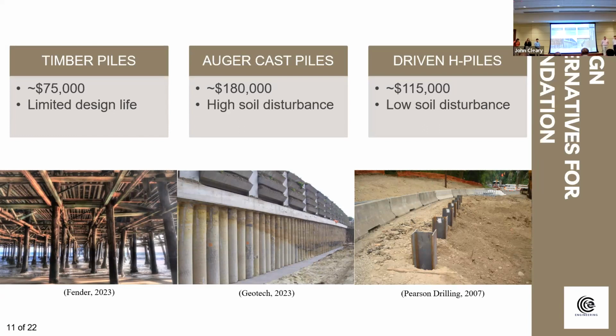So is that what you're referencing here? Yeah. Okay, because with driven piles, the vibrations from the hammer are going to disturb the surrounding soils. So I was kind of confused how you had that as low soil disturbance. You're talking about actually removing soil versus not. Yes, right, not moving soil. Okay.